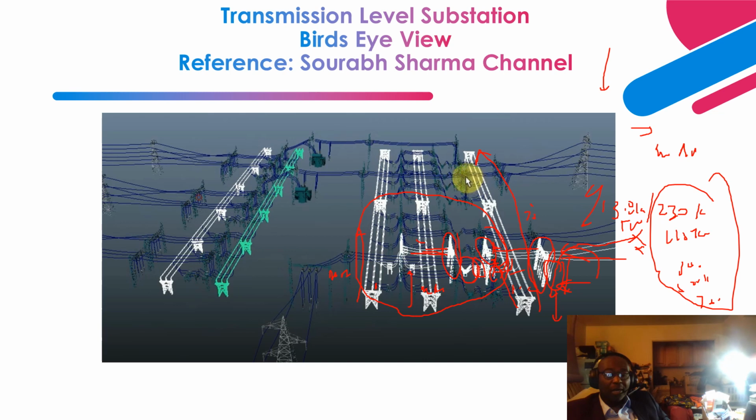This 345 kV line comes in, then it goes through this tower structure. Then we have drop-down conductors that are fed to this second bus, the second main bus, to energize it. So this second main bus, like I indicated, has phase A, phase B, phase C.